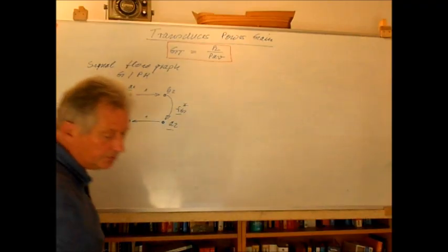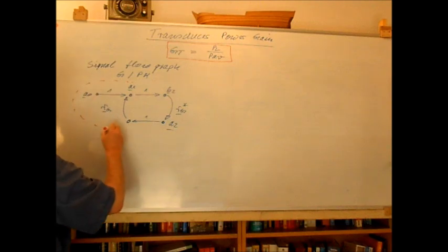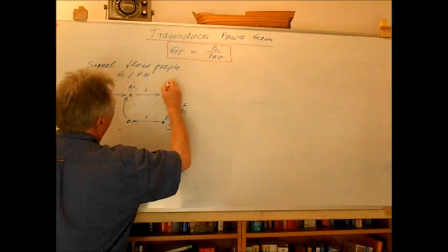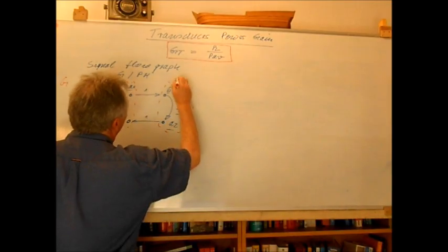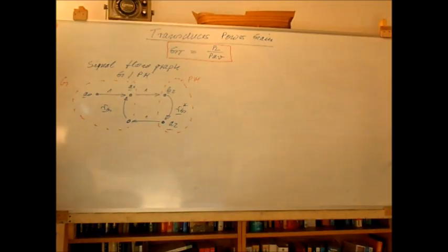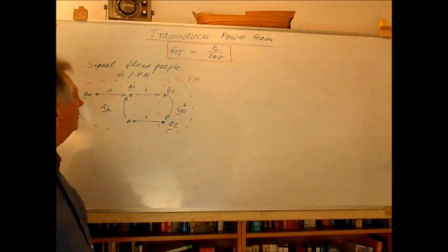So in principle this here is our generator, G, and this is in principle the input of our power meter, PM. And in contrast to the preceding section, I assume that now our power meter would have a certain reflection coefficient, Rg, which is in principle a little bit more general than in the preceding section.